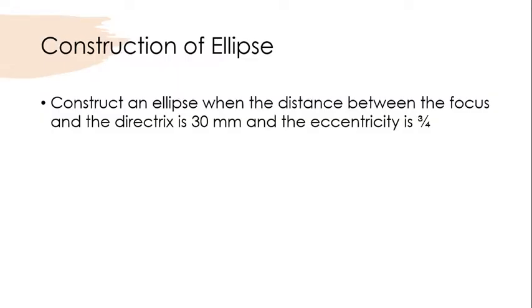So in this class I am going to discuss about construction of ellipse. The question is, construct an ellipse when the distance between the focus and the directrix is 30 mm and the eccentricity is 3/4.